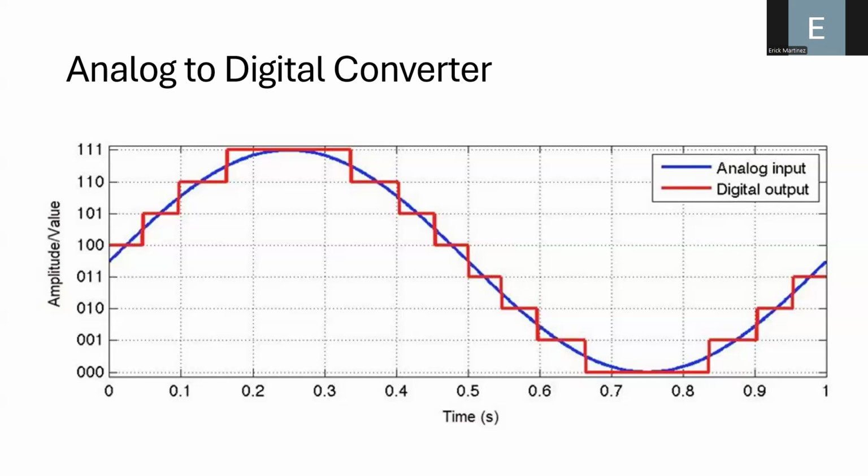But you cannot use, for example, a regular computer to take samples from a sensor, because this computer is not real time. And why is that? For example, you can program a line of code in MATLAB to measure the execution time. But if you measure the execution time once and then measure it again, you will notice that the execution time is always different. The reason is that the processors our computers use are not real time.